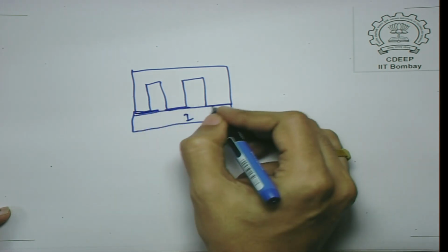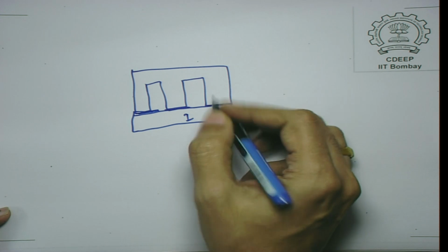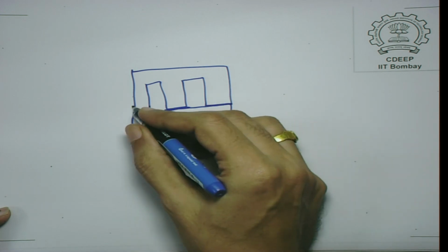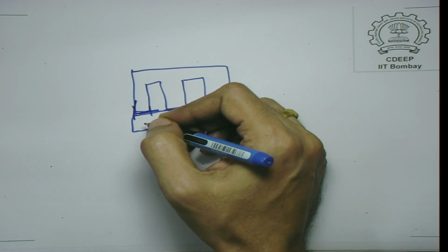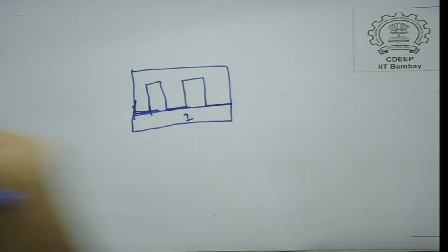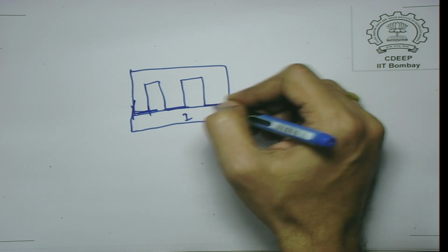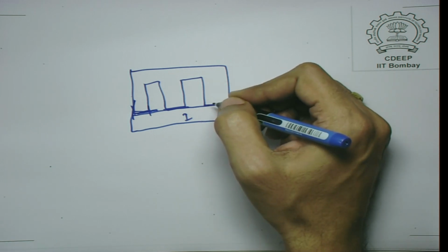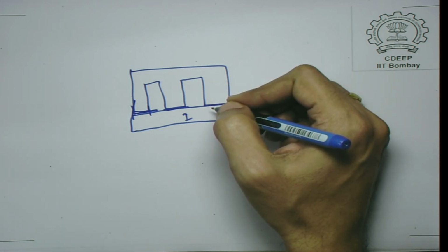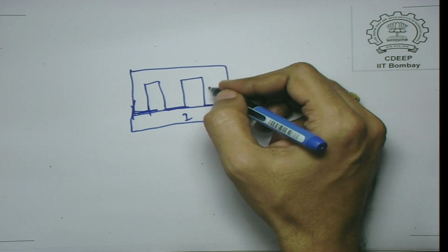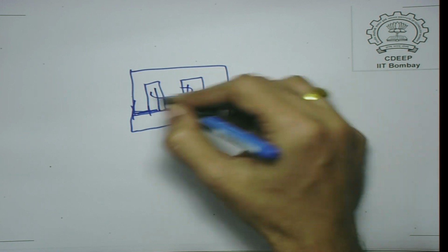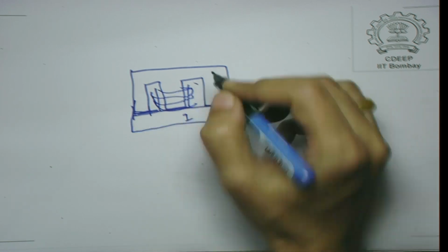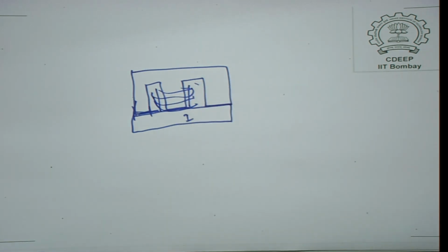We try to press this I lamination against this to avoid any air gap. If there is an air gap here, what we find is that creating a flux in the air gap will require much more current, something I mentioned some time ago, because the permeability of the ferromagnetic material is much higher, and that of air is much lower. Okay. So, this bobbin is kept here and the winding is wound on that bobbin. Okay. So, this is how we make a typical 50 hertz transformer.